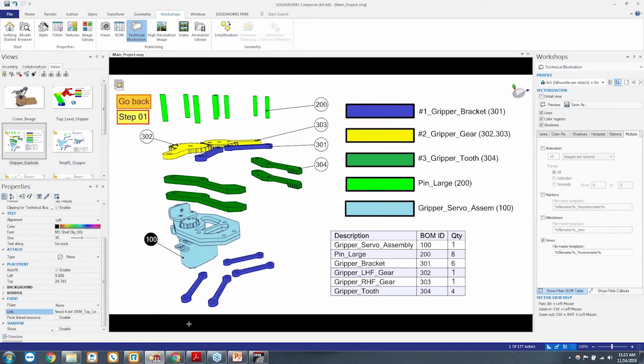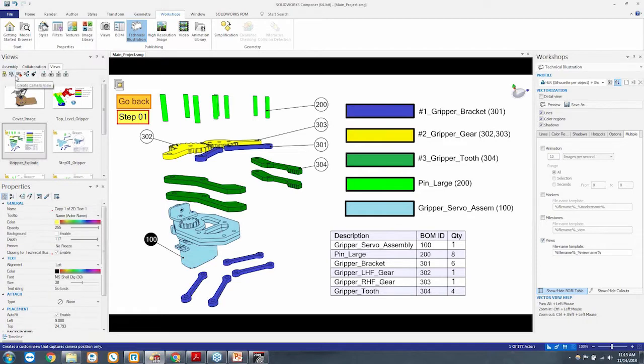And also, if you hit enter, it looks for that file, and if it can't find it, it'll go back to the full file path. So hitting enter is a verification to make sure that it actually is finding that file in that folder. But it is a relative link. So right now, I have everything saved in the same folder, and as long as I move that whole folder together, then there's no problem. And then I just update this view when I'm done. I'll cover that again on the separate assembly.